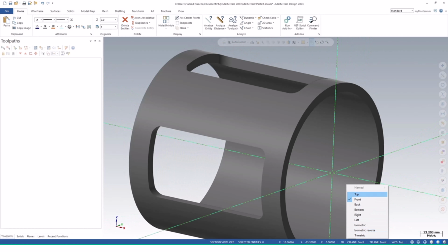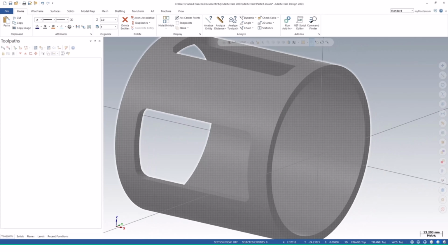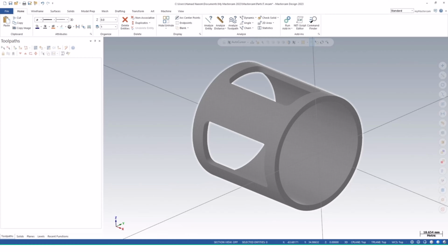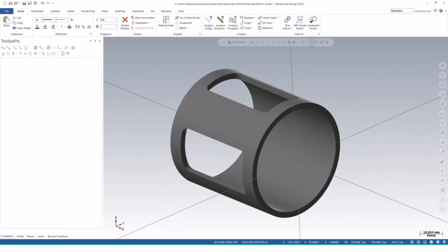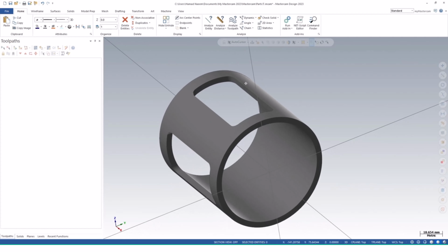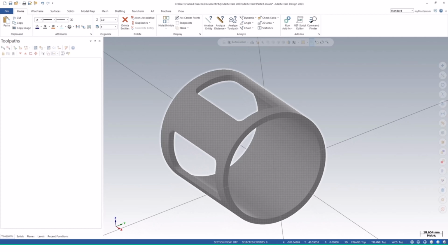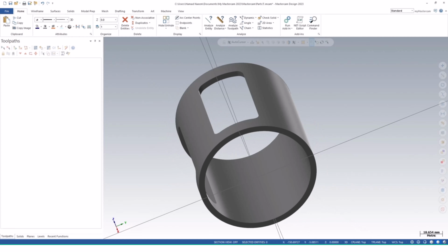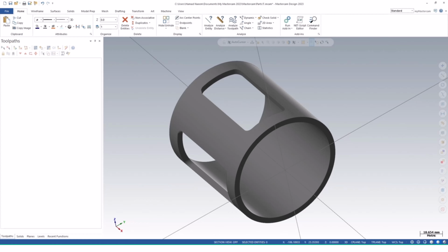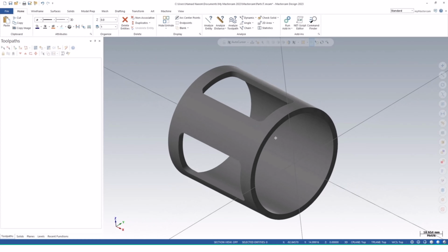First things first, the main thing you need to add in this solid model is a floor for this pocket. In a pocket feature, you have a floor and you have a cut thickness, which we can also call a wall thickness. Actually we have a wall here, but we don't have any floor. It's an open pocket. For multi-axis pocketing, you need a floor and the wall. We have the wall, but we don't have any floor geometry. So we're going to create a floor for this pocket with two pockets.